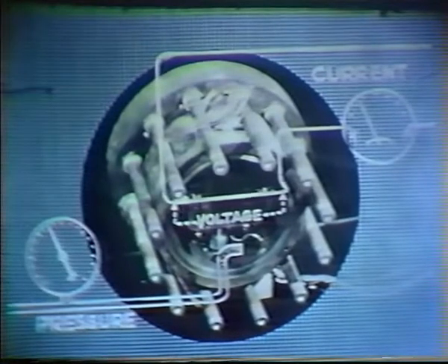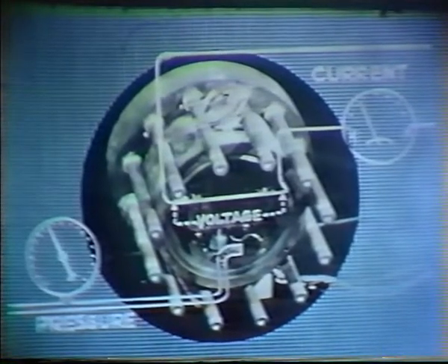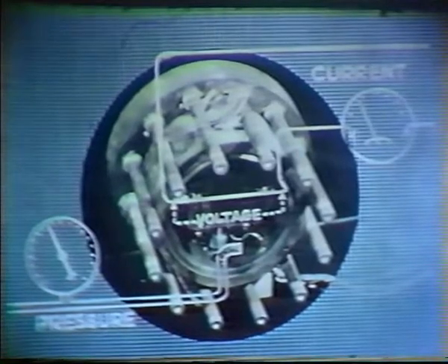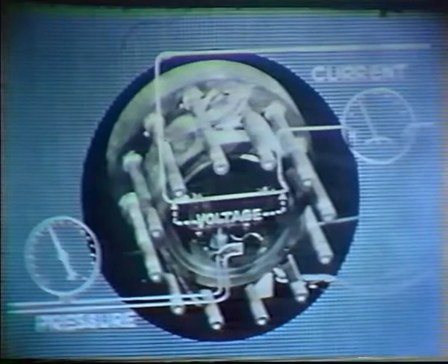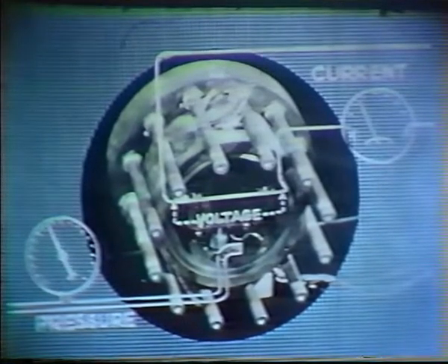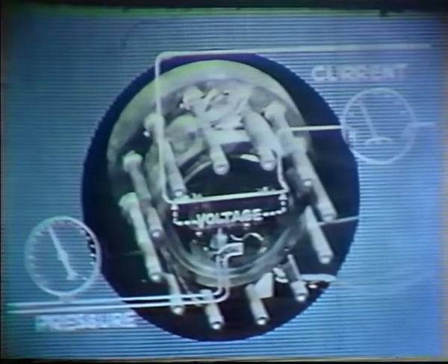Both the cylinder pressure and the heat flux from the wire can be controlled. At pressures less than the critical pressure, the carbon dioxide is maintained at the corresponding saturation temperature. The heat flux from the wire is calculated from the measured voltage drop and current. The voltage drop and corresponding current are also used to calculate the electrical resistance of the platinum wire. The wire temperature is determined from the calibration of resistance as a function of temperature. The experimental results are used to construct a plot of heat flux versus temperature difference.